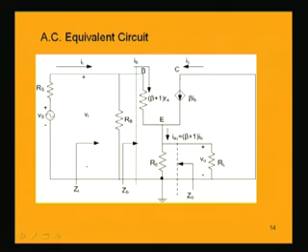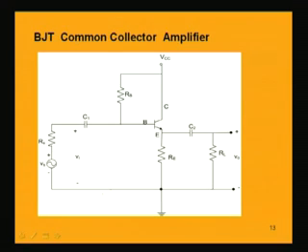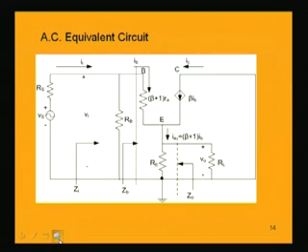Now, the collector is directly grounded and Rc is also not there, so point C is grounded, and the emitter has the resistance Re, because in this circuit the emitter has this resistance Re and the capacitance C2 is shorted. It also has the resistance RL, which is now in parallel with Re and connected to ground. So RL and Re are parallel and connected to ground.